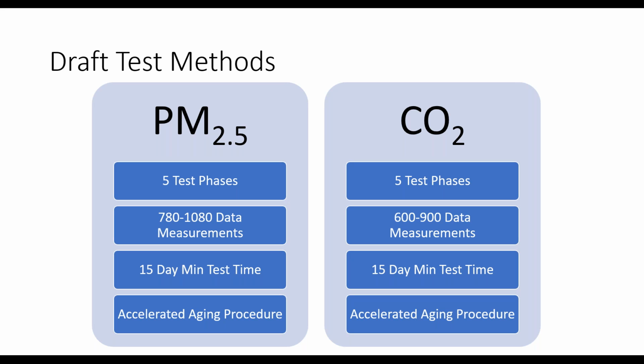So we wanted one that dealt with aerosols and then another that would deal with some sort of gas. And we picked CO2 not because it's necessarily a pollutant that has a dramatic health effect, but because there are a number of CO2 sensors on the market that are low cost with quite a lot of variation in the quality of those sensors. Some of the other gases that were present, we felt like had at least more sophistication in their sensors. Other ones didn't have many sensors on the market. And then there were some practical limits, like formaldehyde we would have loved to deal with, but the reference sensor that we would need to compare against was cost prohibitive.